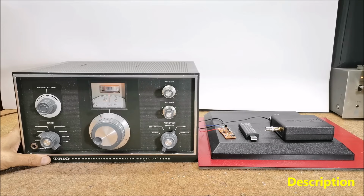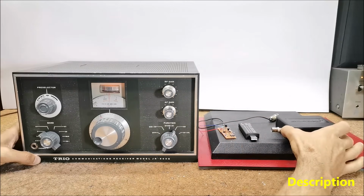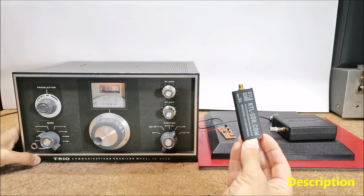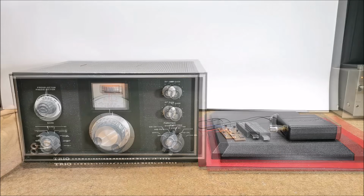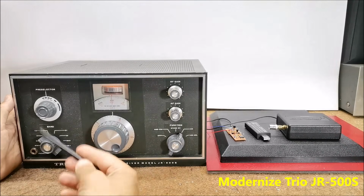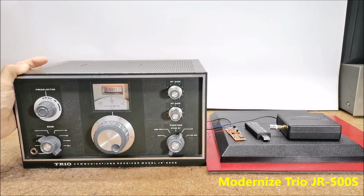Specifically in this project, I developed a software-based Panadapter using my SDRplay SDR radio receiver, but as I mentioned earlier, another type of SDR radio can also be used, such as a cheap RTL-SDR dongle with appropriate software. This time I decided to modernize my old vacuum tube high-frequency receiver, model Trio JR-500S. An excellent explanation of how to install it and how the Panadapter works can be found on Scott Baker's website, from where I took the input part of the buffer and some pictures.